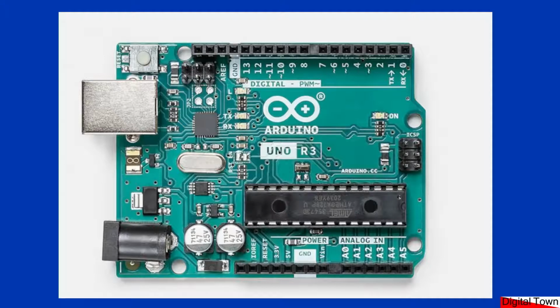So our digital pins, the lesson that we're going to have today is about using those digital pins as an on-off switch, and the pin that we're going to concentrate on today is pin 13, so that we don't have to start adding components and building circuits. So let's switch back to the Arduino IDE and we'll get started.